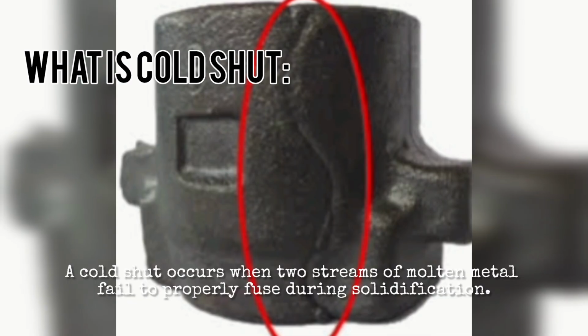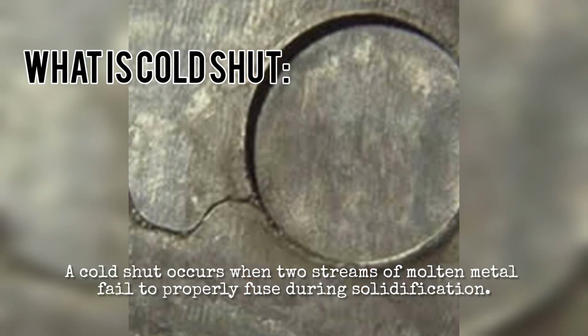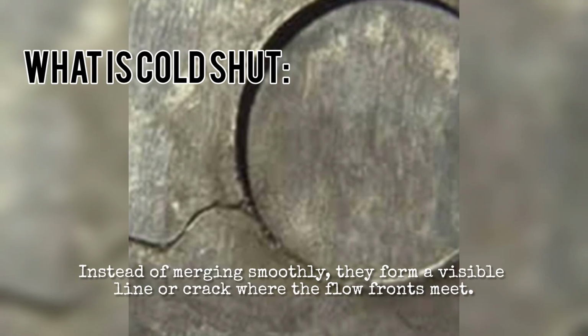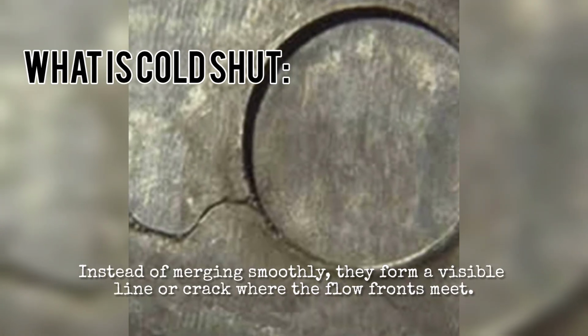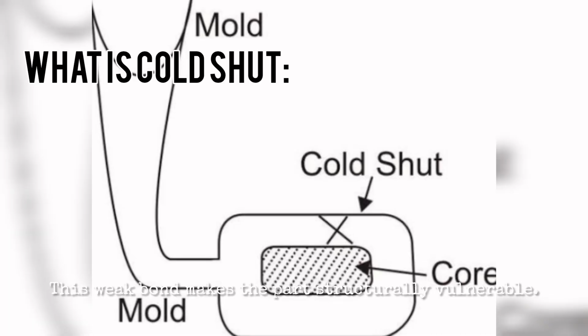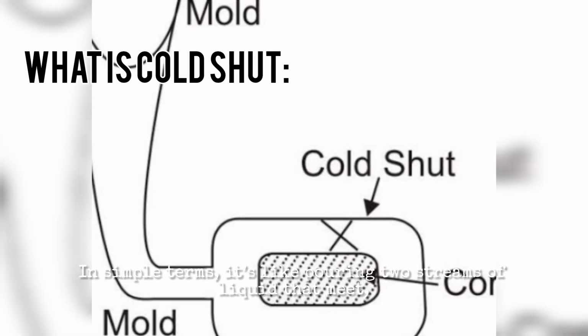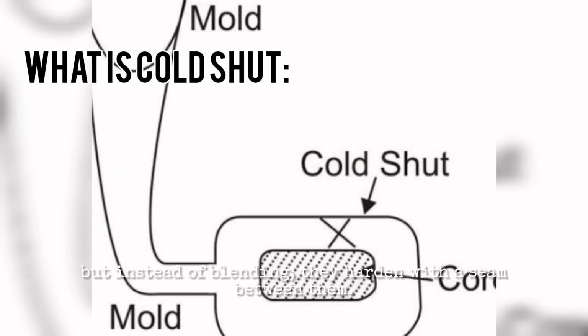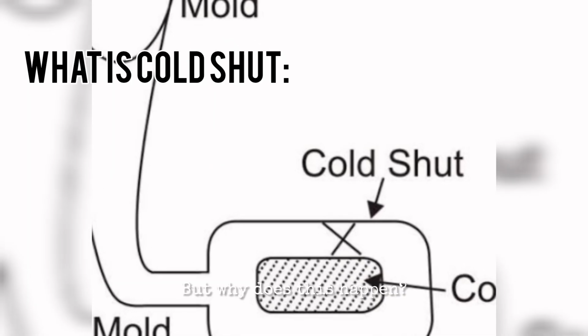A cold shut occurs when two streams of molten metal fail to properly fuse during solidification. Instead of merging smoothly, they form a visible line or crack where the flow fronts meet. This weak bond makes the part structurally vulnerable. In simple terms, it's like pouring two streams of liquid that meet, but instead of blending, they harden with a seam between them. But why does this happen?